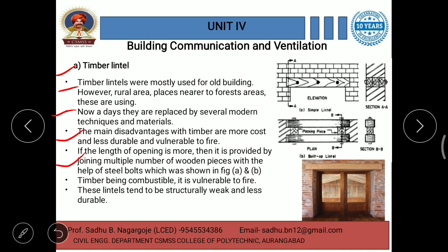If the length of opening is more, then it is provided by joining multiple wooden pieces with the help of steel bolts. Okay, with the help of steel bolts, you can see in these plan and section diagrams. Then timber being combustible, it is vulnerable to fire. These lintels tend to be structurally weak and less durable. Okay, as they are made up of wood or timber, that's why structurally they are weak and also less durable.